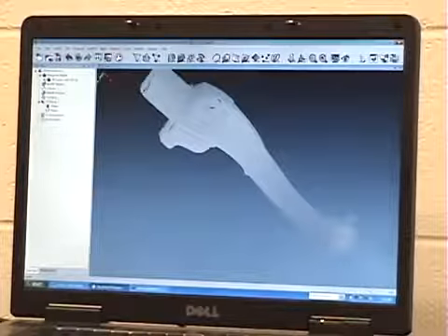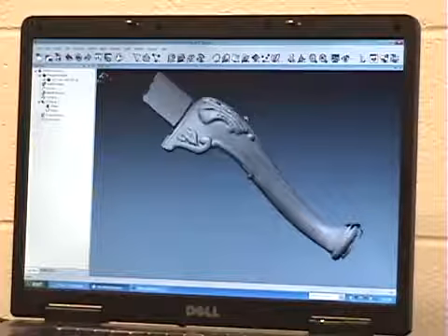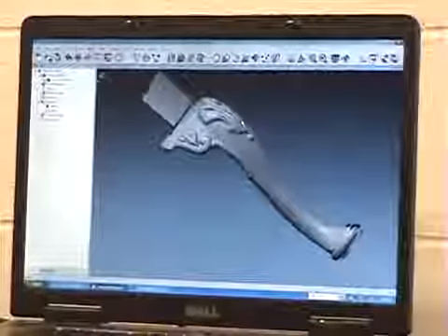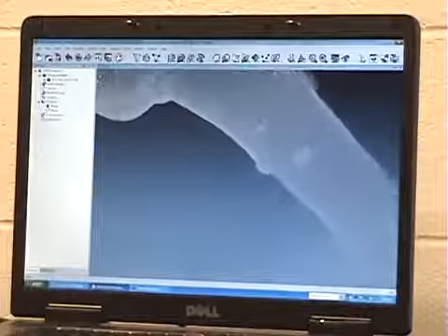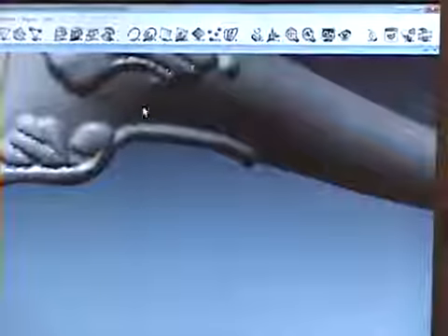Okay, this is the layout after the file's been mostly cleaned up. It's opened up now in a software called Polyworks, and you can see that if you look real closely, these are all triangles, triangulated mesh that's been cleaned up and patched. The software has a lot of tools that can go in and actually close up holes in the geometry, and it makes the post-scan a much more efficient method.